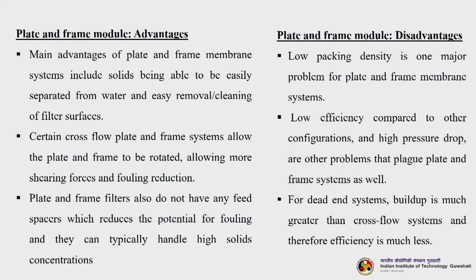So, the main advantage is that solids are easily separated from water, and there is easy removal and cleaning of filter surfaces. Mechanical cleaning is very easy. Certain cross flow plate and frame systems allow the plate and frame to be rotated, allowing more shearing forces and fouling reduction. Plate and frame filters also do not have any feed spacers, which reduces the potential for fouling, and they can typically handle high solids concentrations.